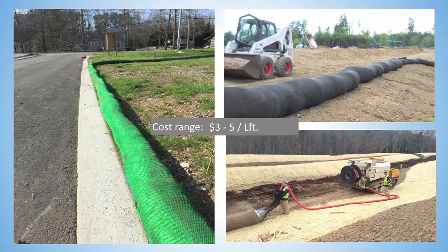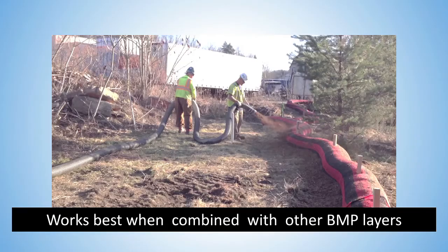They're a little more expensive, but again, they're going to last you a long time, and they're going to survive for over a year or more on a lot of these sites. Again, these work better when combined. Here they're blowing some straw on the uphill side of the project to reduce the amount of soil going to be dislodged by raindrop impact.